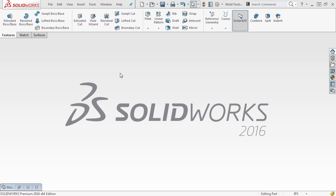Now, the reason I say this is because there are several different types of, for instance, injection molding. You have a lot of short run or pre-production injection molding houses. These are ones that use aluminum tooling, so they're only set up to do between 100 and 500 parts. They don't use liquid cooled molds, and typically their restrictions in terms of side pulls or geometry that they can get away with are much more limited than, say, a full production run that's going to crank out thousands of these things a day. So when you talk about the final tool house that's going to be doing the job and knowing their limitations, that can go a long way in how you design your part.